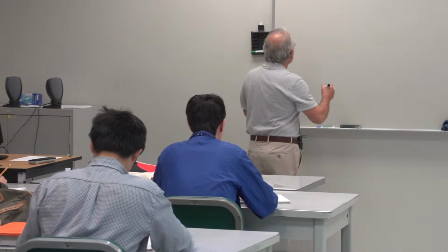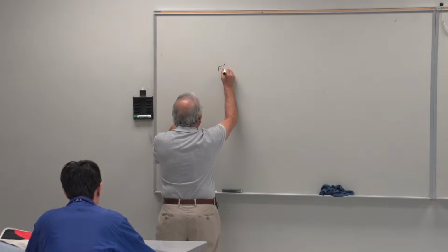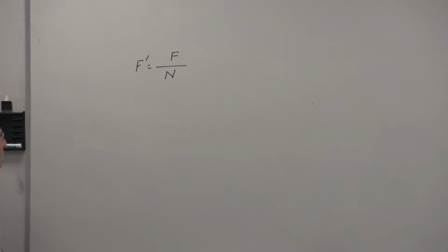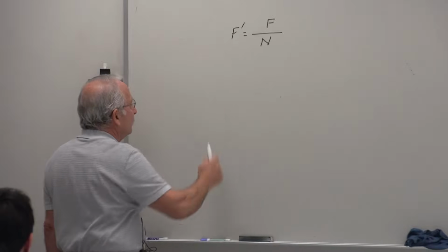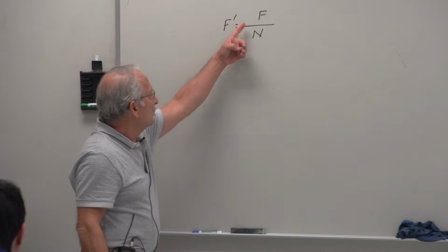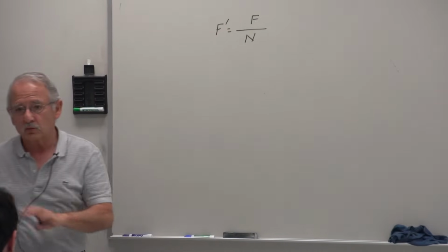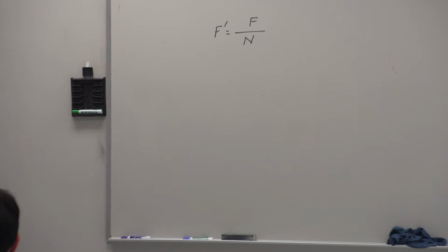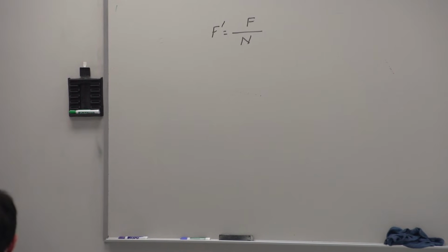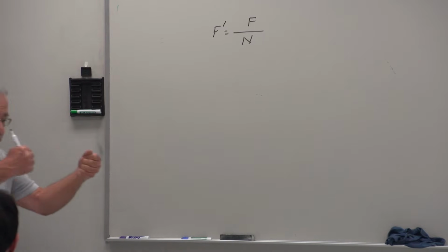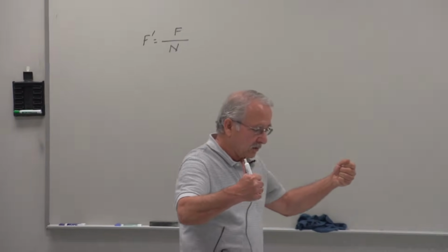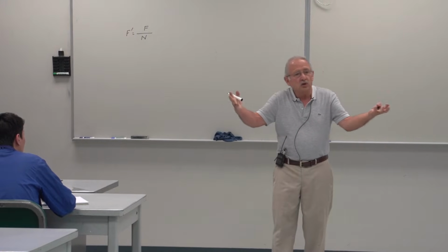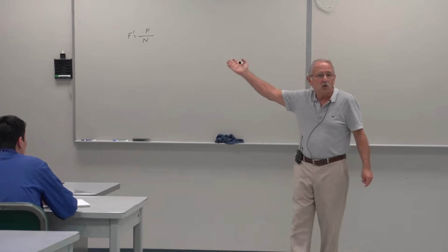So we had what we called the primary load. F is the external load. Primary load for each bolt is equal to that external load divided by the number of bolts. Straight division. Now, there may or may not be a moment generated as well. For example, if the connection is under straight tension, no bending moment, then this is it. That's all you get.